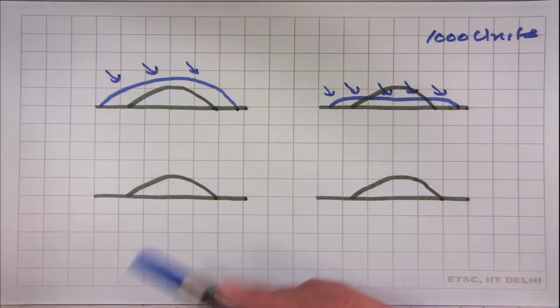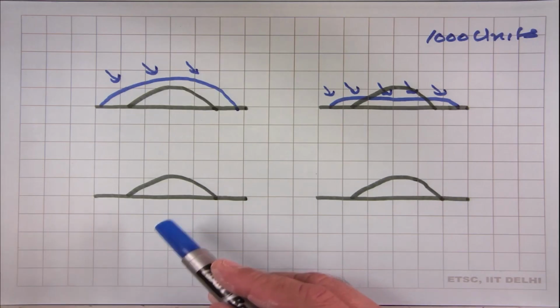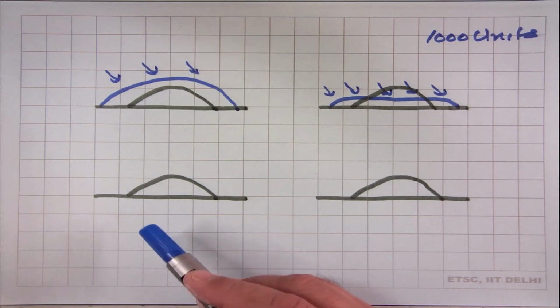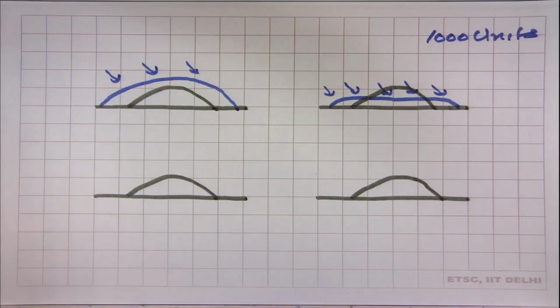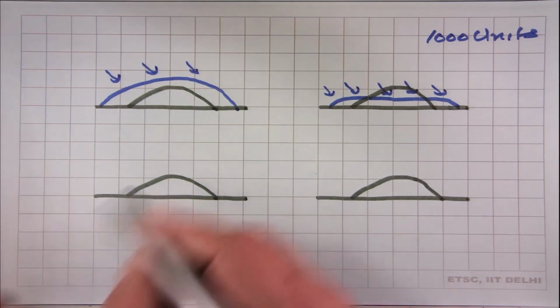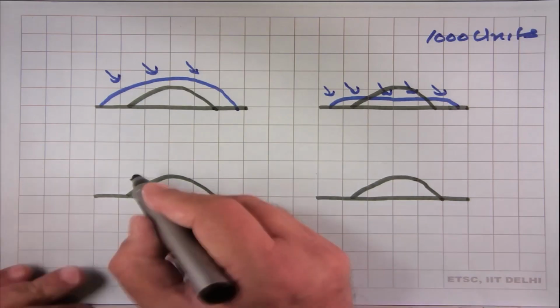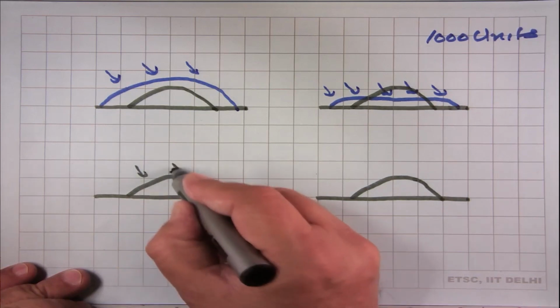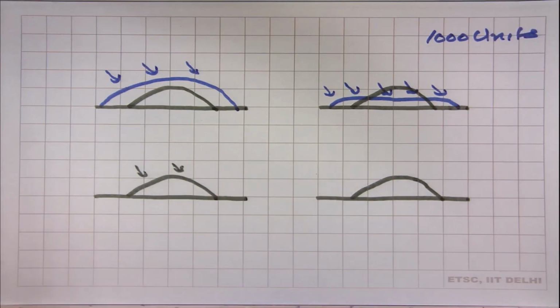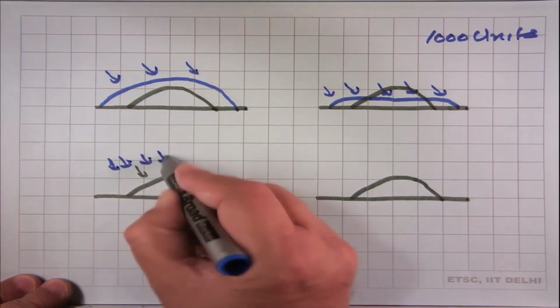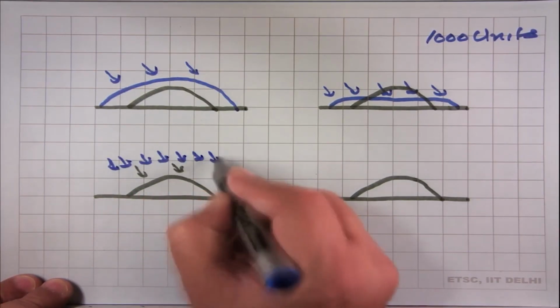So the same waste dump in a different location will get different impacts. So quantity is not the issue. The quantity, the surface area, the amount of rain. So if in Rajasthan you are having this much rain, in Bombay you'll have more, so this will produce more leachate.